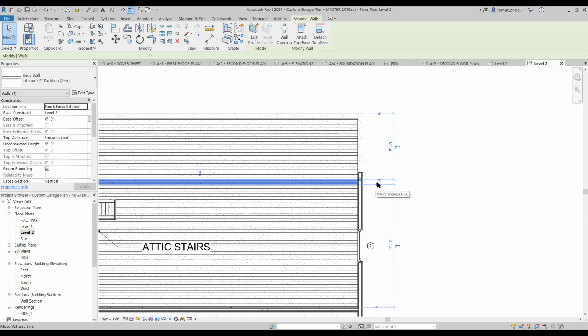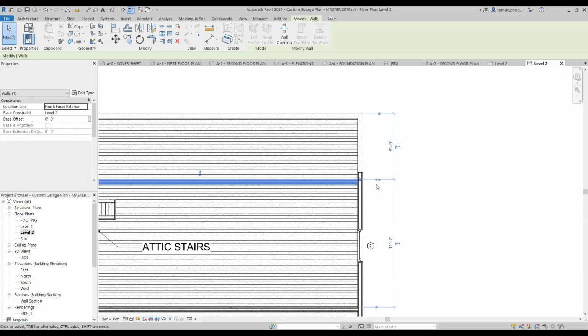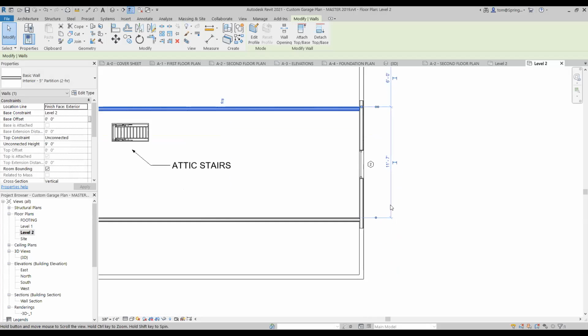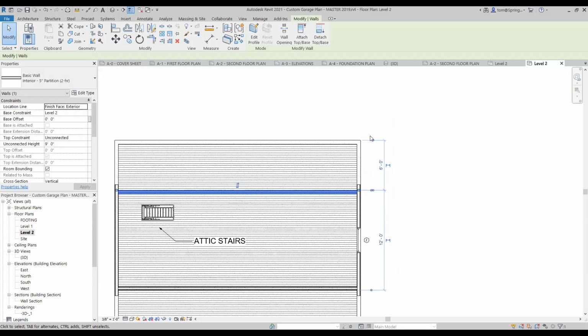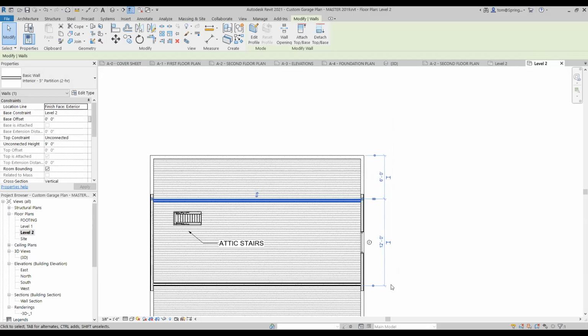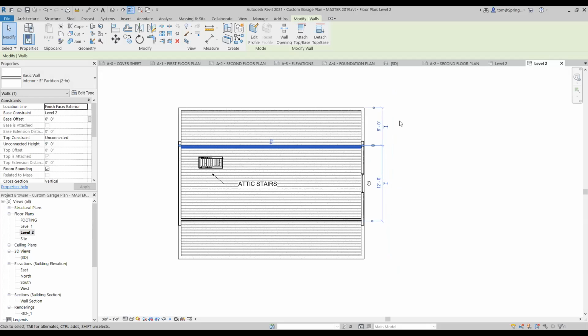And then these right here should meet. And then this one would go over to here. And this one is 12 feet, okay? So it's essentially 6 feet from the outside to what would be the outside wall, and then you have 12 feet outside wall to outside wall, and then outside wall to outside wall. So 6 feet, 12 feet, 6 feet to get the 24-foot dimension. Okay, so that's what we have there.